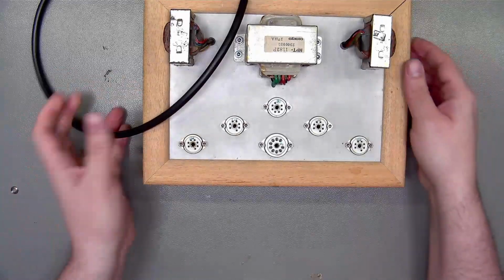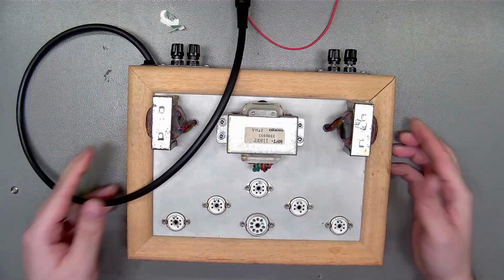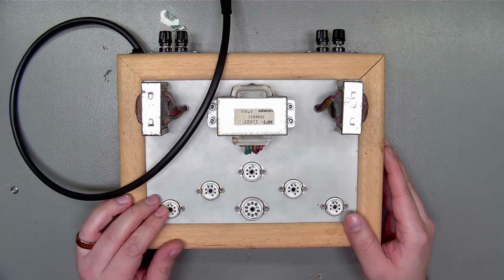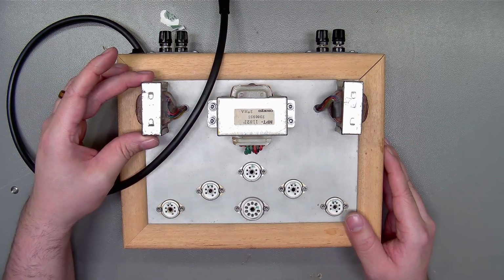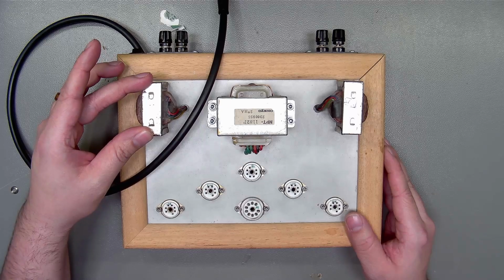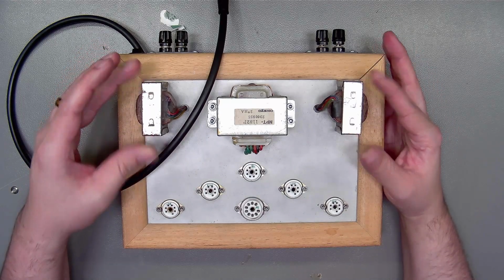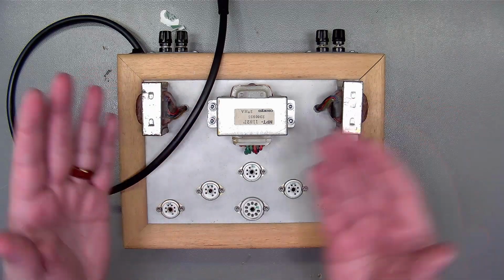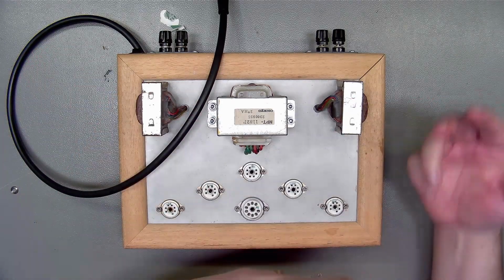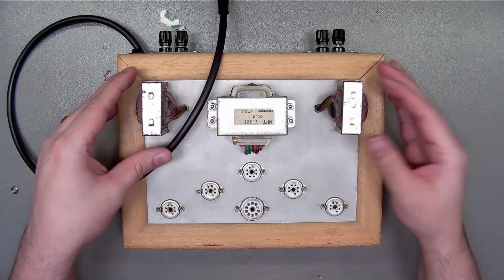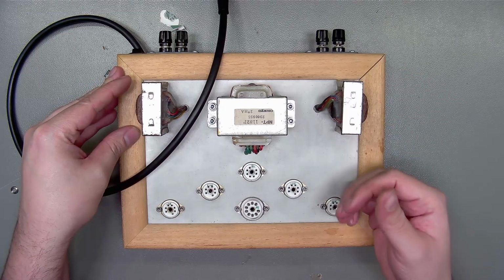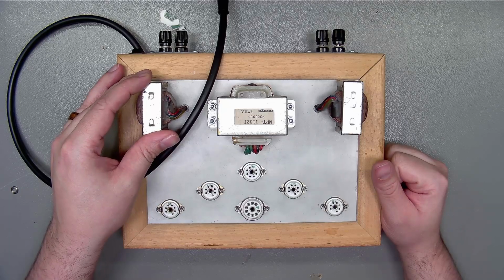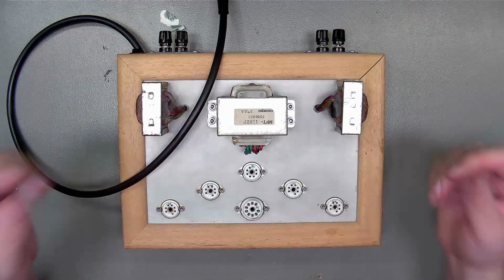So, how do you get started building a tube amplifier? Well, if you have parts already lying around, the first thing you need to know is, what are my output transformers? You have to measure them and see what impedance ratio they have. What is the primary impedance? Ideally, what is the secondary? But usually you can just guess if you do not have the original speaker it came with. And even if you have, most of them have no markings about the impedance. So yeah, good luck finding that out.